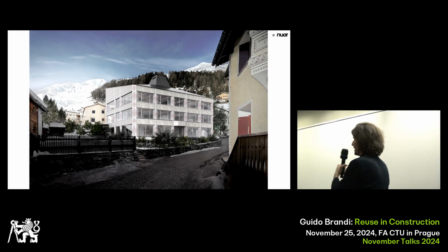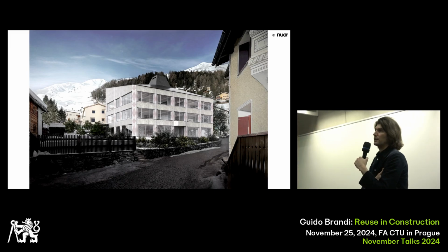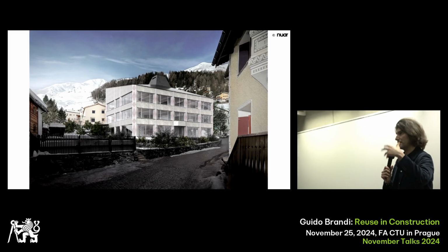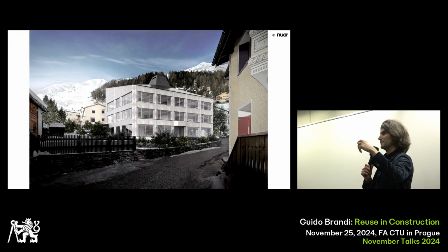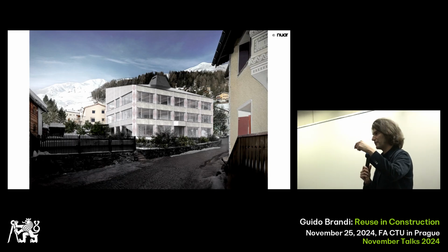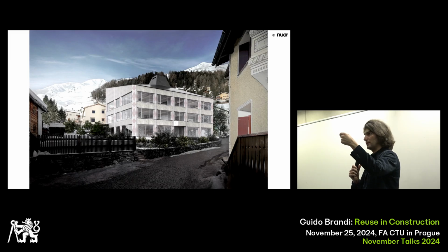to calculate the emissions of this building, we follow the system that we have in Switzerland. We have a table from KBOB, the public organ of all the public clients of Switzerland, that organizes this table that you can download, where you have the UBP value, or in European terms the ADP, and you can have for every different material the CO2 equivalent emission.